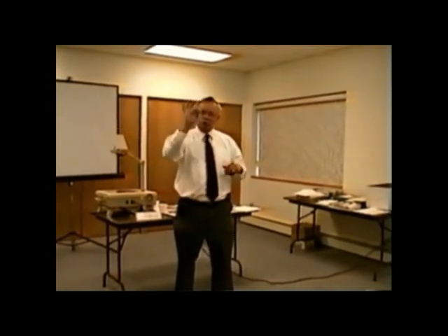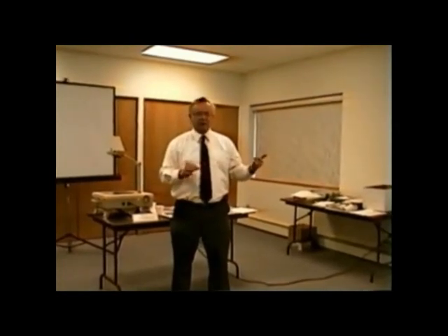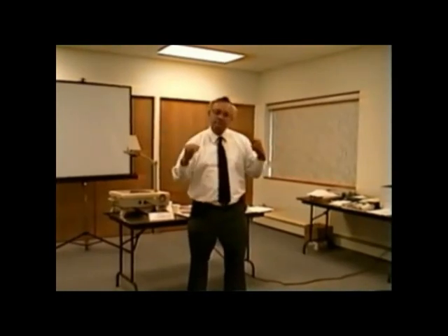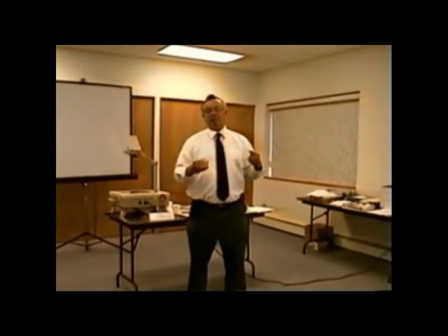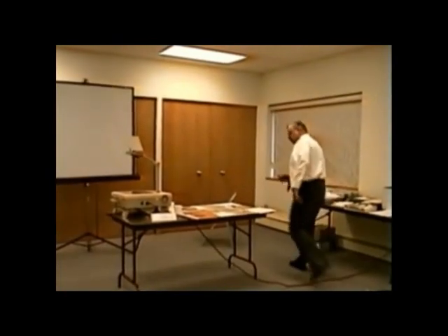Okay. But micro isn't 1,000 and milli is 1,000, we're not talking about milliamps here, we're talking about microamps. 2 to 4 microamps, as low as 0.2, 2/10 of 1 microamp. So a microamp is 1 millionth of 1 amp at 24 volts. Okay? So again, we're talking about a very small portion.